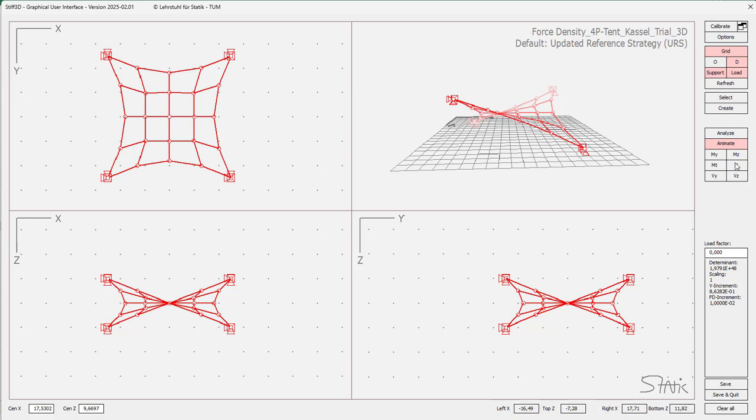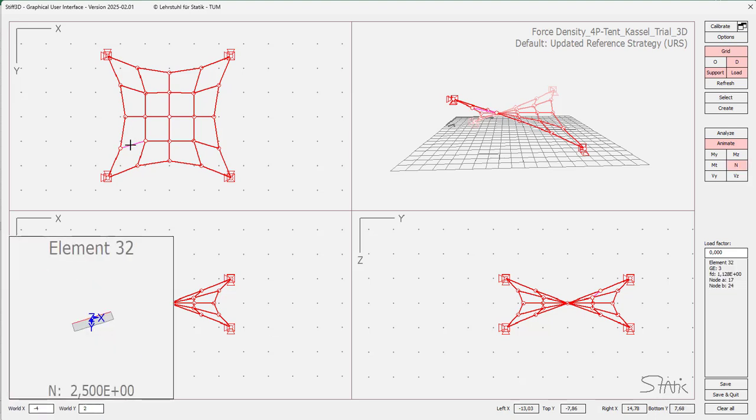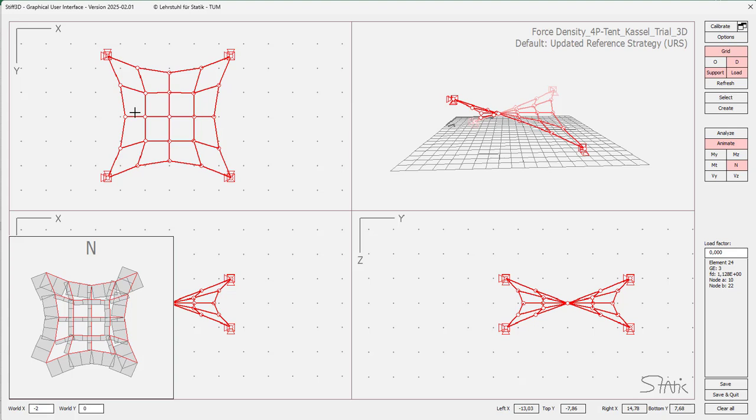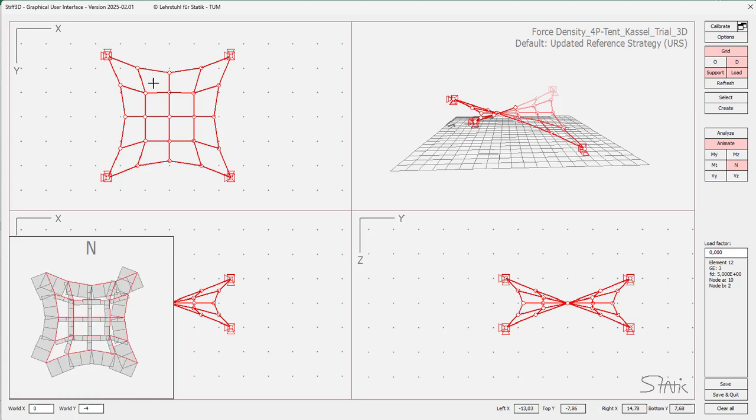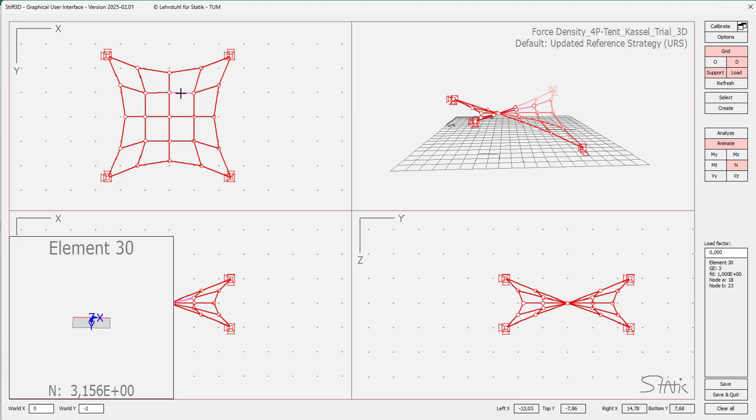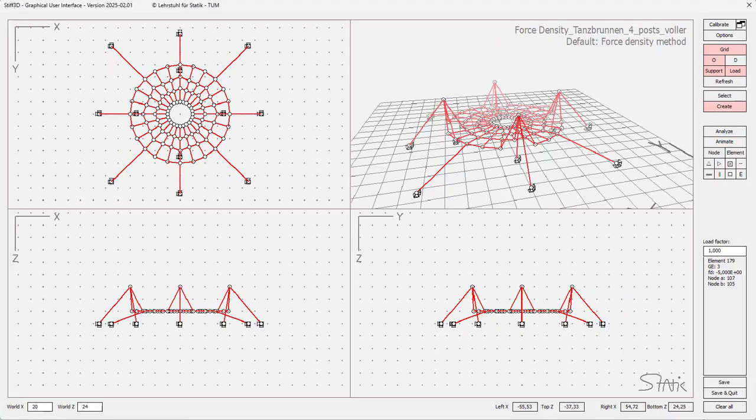And if you check the forces of the cables, then you see that the unconstrained elements, of course, have reached the goal forces of our procedure, while all the constrained elements deviate from the goals. At the edge we had 12.5. You see these are considerably deviated from this value due to the constraints, and the constrained inner elements, which are supposed also to be at 2.5, that's the goal value, also of course deviate considerably from these goal forces because of the constraints. That is consequent.